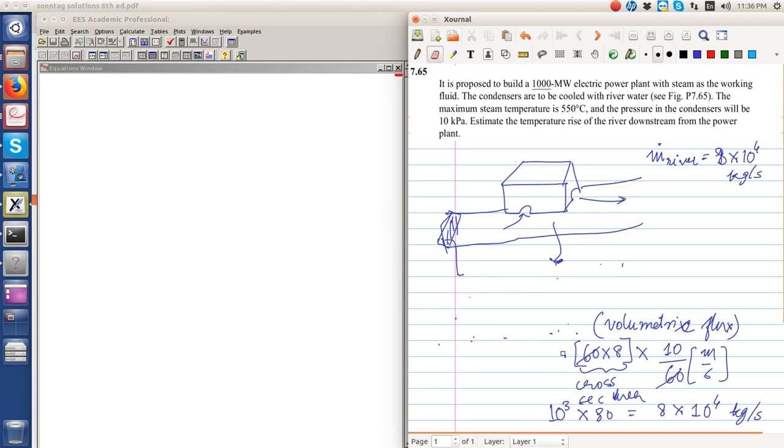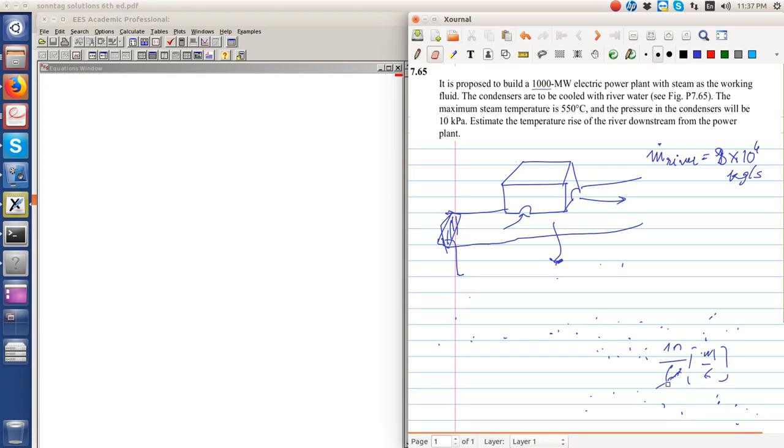So the idea behind the problem is, the pressure in the condenser is given. We are given the maximum temperature of the boiler. The pressure of the condenser should correspond to a temperature in the condenser, because the things in the condenser are in the two-phase zone. If we assume everything to be a Carnot cycle, things are very easy, because we can then relate the temperatures to the works done.